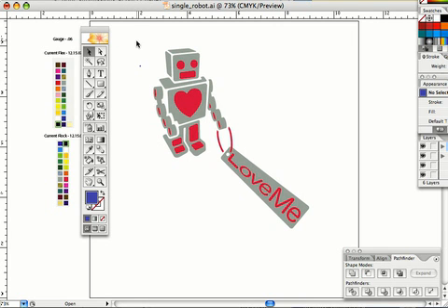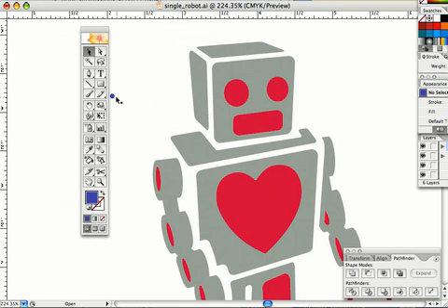Okay, so I'm going to show you how to use this gauge. When you do your design, anytime that you have 2 pieces, especially colors, you want to make sure that there is at least a 0.06 all around the design. So let's say this red eye, we want to make sure that before it hits that next red color, there is that much space in there. The same with all these other ones. Because basically when it plots, it's going to cut out of a giant sheet of vinyl.